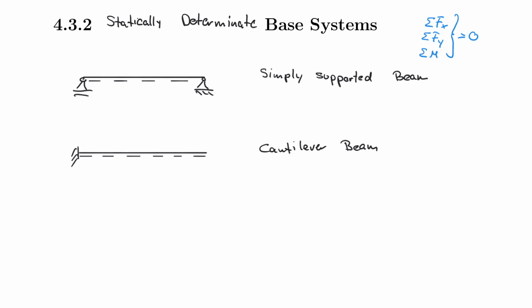Now there's a third system which I will only draw here for your reference. We will talk a little bit more about this, but that is a beam that looks as follows. It is kind of resembling a roof structure. And what's important about this beam is 2 things, as you will understand in just a little bit. It has a hinge here on the top. So this here is a hinge. And now I will actually introduce a pin here, and you know that this has 2 support reactions.